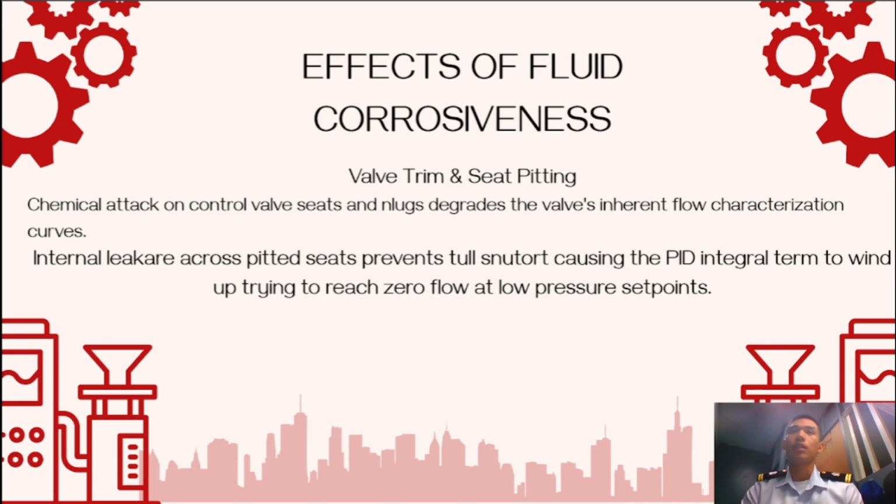Next is valve trim and seat pitting. Chemical attack on control valve seats and plugs degrades the valve's inherent flow characterization curves. Internal pitting across the seats prevents tight shutoff, causing the PID integral term to wind up trying to reach zero flow at low pressure set points.